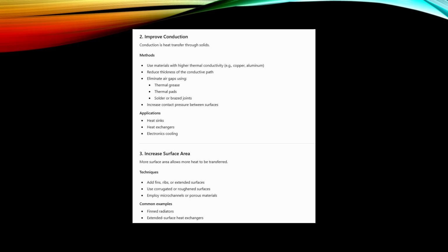And remember always to eliminate air gaps between materials. Use thermal grease, thermal pads, or solder to ensure that you have a good connection between materials.